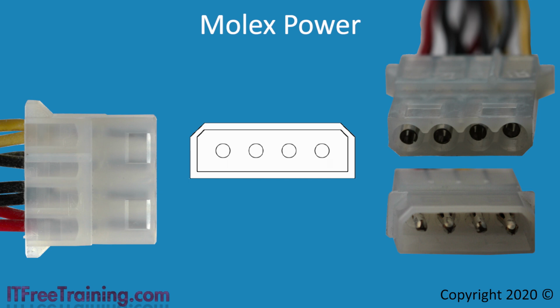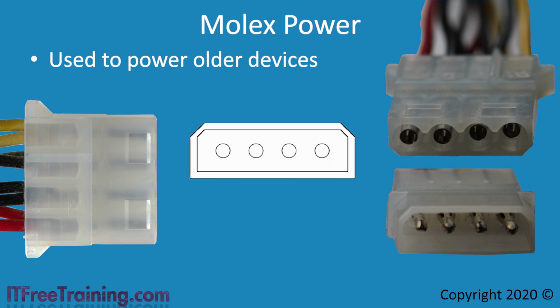Although this Molex connector in the old days was quite popular, nowadays this connector is only used on older devices and some internal fans. Due to the way the connector is designed, some force needs to be used to plug and unplug these connectors. To prevent the connector being put in the wrong way, there are chamfers on one side of the connector. A chamfer is essentially an angular notching on the connector. You can see that these make the connector angular at the top. When inserting these connectors, make sure that the chamfers line up.